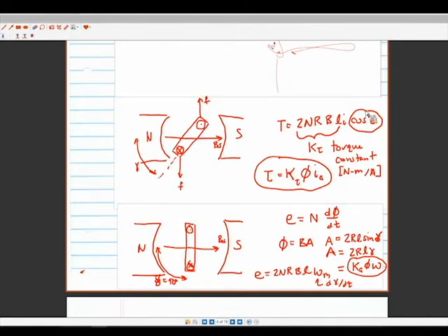If we have something that's activated by an external flux from an electromagnet, the torque constant is actually going to be completely different units. So I can't really give a straight answer because it depends on the type of motor. For this problem, use the bottom one: torque is equal to torque constant times the flux times IA. We'll make it clear in the problems that we give.